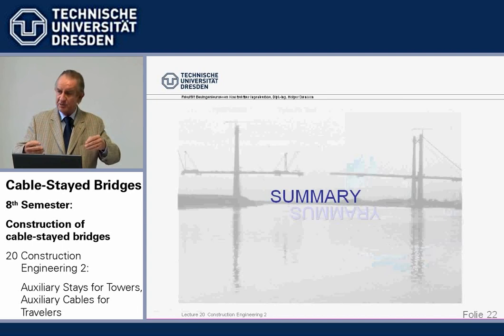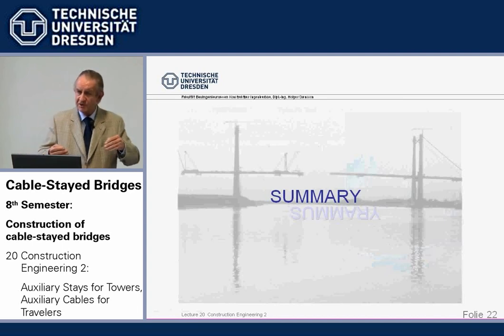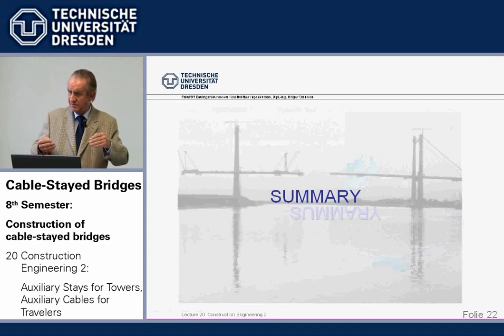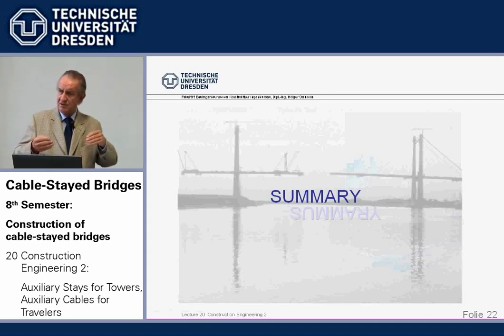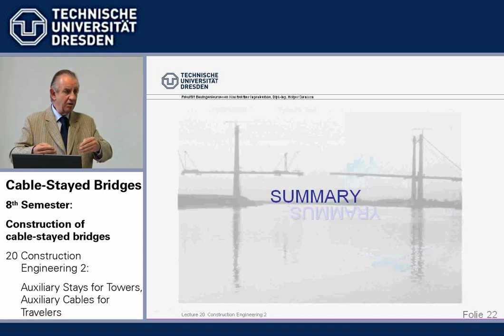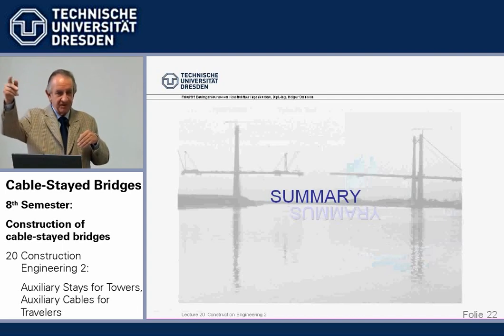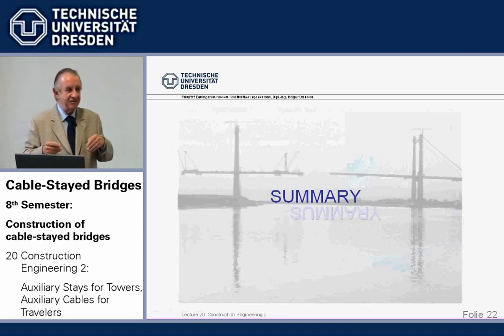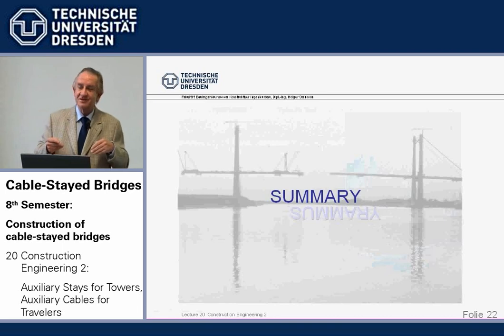So we use a computer, and I've shown you what commands you have to give the computer to apply loads, to open joints, to be able to take out elements, and in this way to dismantle the bridge. And we know at the very end all action forces must be zero. If something is still fiddling around in the air without a member, something is wrong. It's a very simple and very helpful criterion.